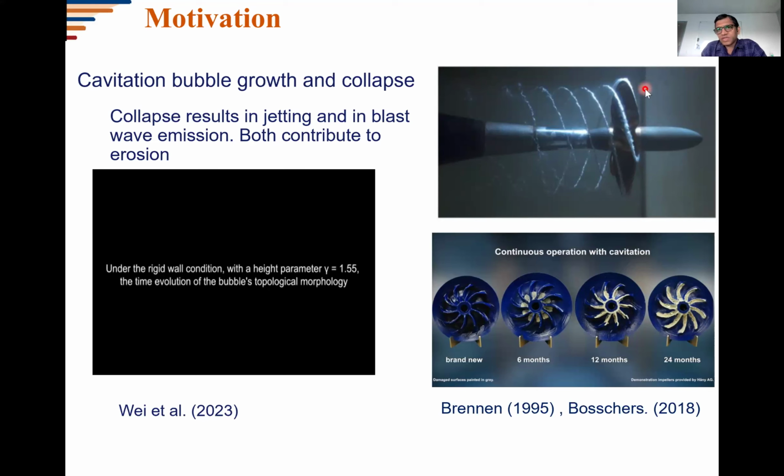whenever we have something like a propelling device in an underwater scenario, you would get this helical train of bubbles behind its wake, starting from the tip of this propeller, and these cavitation bubbles that are formed because of the cavitation inception events that take place on the propeller tip are known to lead to structural damage.